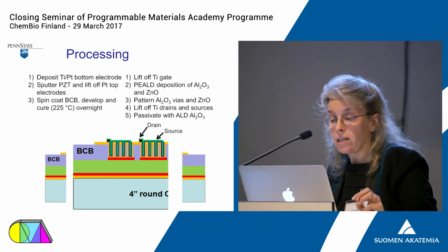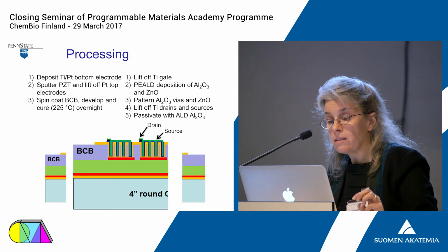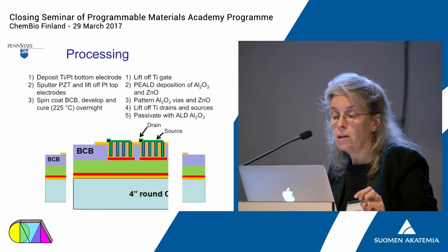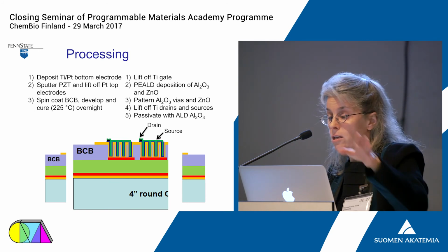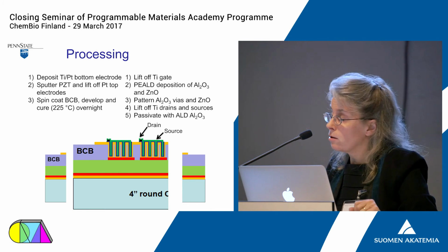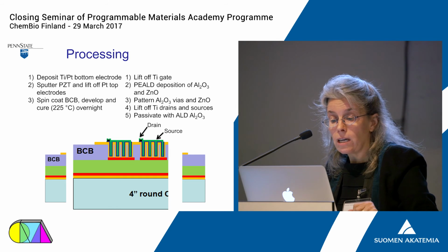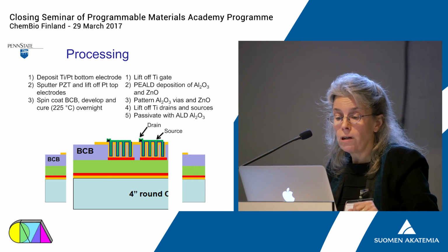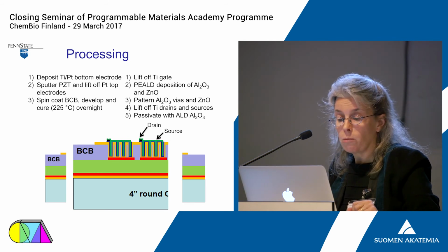We then deposit the titanium gate metallization and pattern that, and then with plasma-enhanced atomic layer deposition, deposit the gate dielectric and the semiconductor, pattern those, and then lift off the titanium sources and drains, and then the entire thing is covered with a layer of alumina for protection. So this shows an example of a 5x5 array of piezoelectric actuators on a 400 micron thick piece of glass for use in this X-ray telescope application.